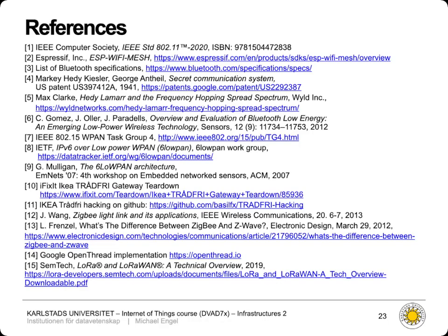If you want to experiment, there's quite a number of links like reference 10 and 11. That's essentially people trying to hack on the whole home automation hardware from IKEA. So please take care when you experiment on light bulbs because these are operated on just mains voltage, so 230 volts. So this can be very dangerous. So obviously you have to apply precautions and power the devices, for example, only from a 5-volt device. And this is also mentioned in the hacks here. So if you want to experiment with this, please stay safe.